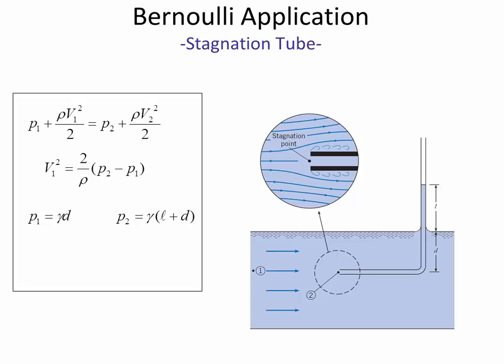So the pressure inside the tube down here is bigger than the pressure at 1. And that's true even as we go horizontally. Remember that there's no change in pressure inside the tube; it's this special static environment. So if we substitute these two terms into Bernoulli's equation, that's a way of knowing what the velocity at 1 is. You can measure the velocity just by knowing the density characteristics of the liquid and how high above the liquid surface that it rises to. And so we can simplify even further that the velocity at 1 is the square root of 2gl.